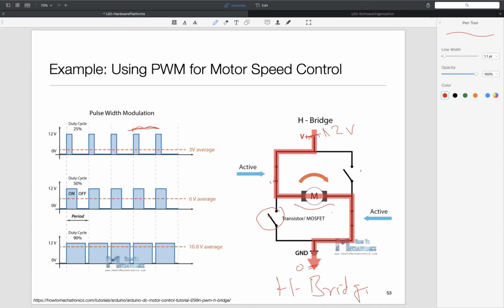My responsiveness is slower. So if I need rapidly changing analog values, I can't do it this way. But things like light and motors operate at a much slower scale. Their dynamics are in the millisecond range, so it's perfectly fine. PWM works very well for this class of application. On the other hand, if you need a more agile analog signal, then you should use a proper D2A converter.